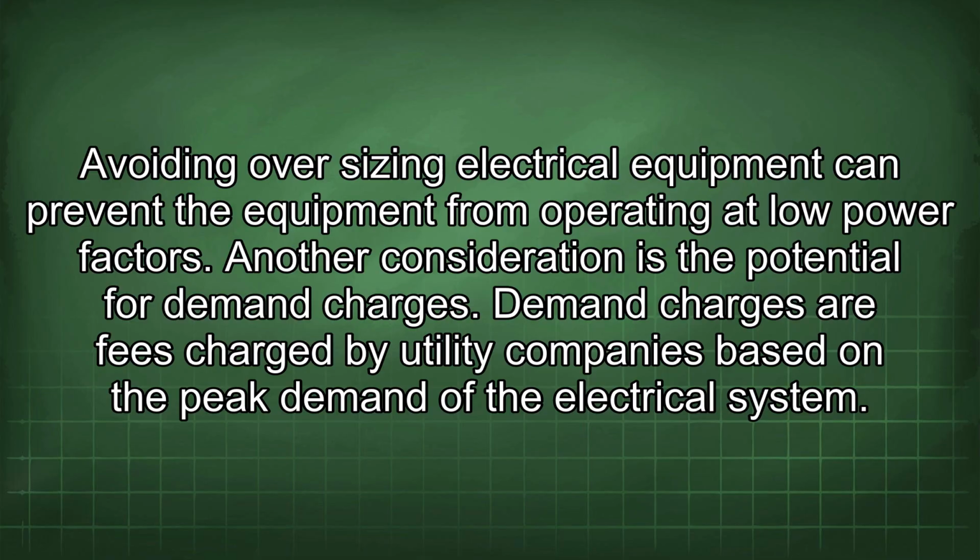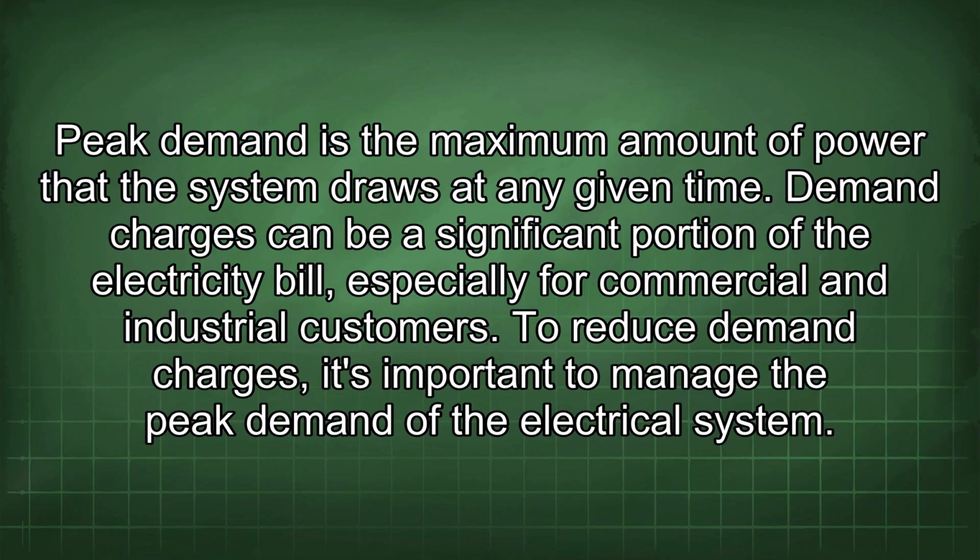Another consideration is the potential for demand charges. Demand charges are fees charged by utility companies based on the peak demand of the electrical system. Peak demand is the maximum amount of power that the system draws at any given time. Demand charges can be a significant portion of the electricity bill, especially for commercial and industrial customers. To reduce demand charges, it's important to manage the peak demand of the electrical system.